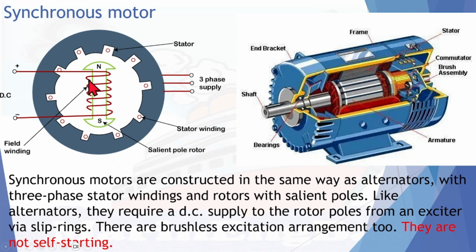It will never start spinning unless you first drive the rotor by external means. You have to drive the rotor by external means, then it will have inertia. So now it's under rotating situation. Then if you energize this one, apparently this rotor magnetic field will also be rotating, and there will be a difference,